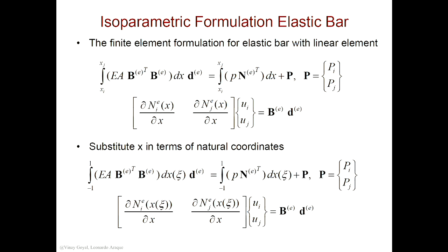Very simply stated. But now we have to keep track that these shape functions are now a function of c, and this dx here is dx/dc. But all I've done is substitute x in here. And just by doing that, I have changed the limits of integration. If you go back and revisit your calculus class, that's exactly how you did it.